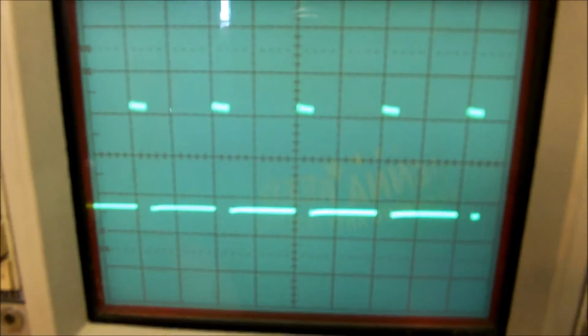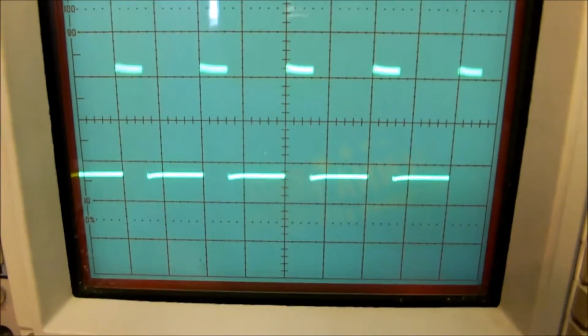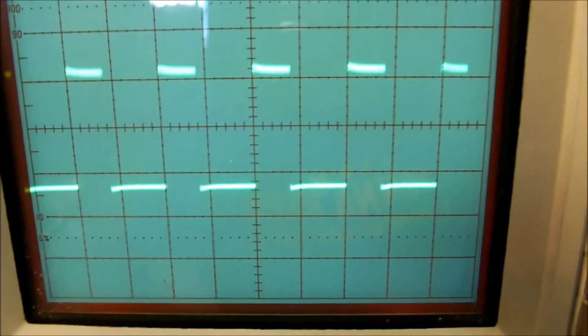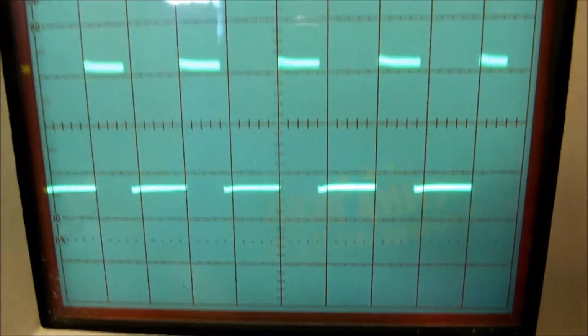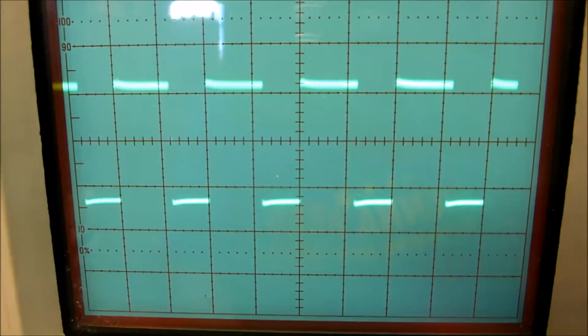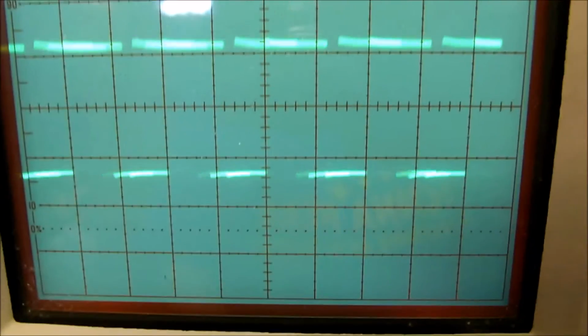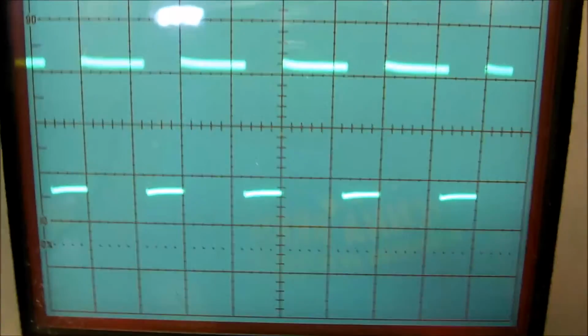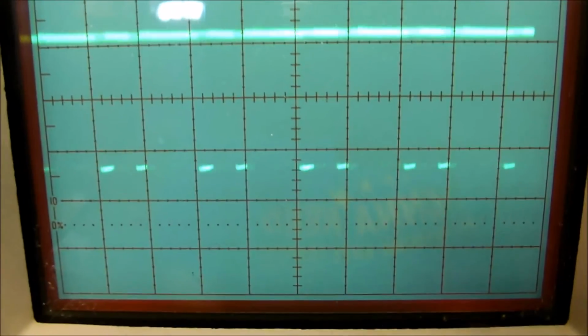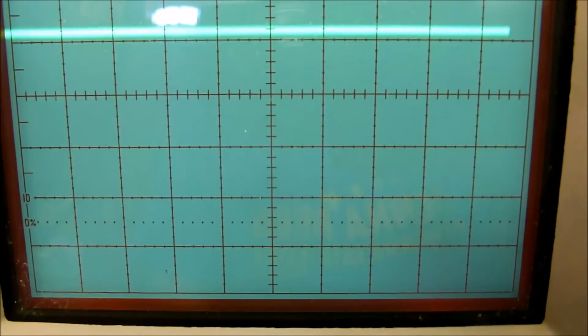Notice as I try to hold this up to get rid of that reflection. Notice as the pulse width increases, the motor will slowly start. I get to the start threshold, and it will continue to gain speed and torque. Actually, low speed will, but you always have a lot of torque, a lot more torque at the lower speed than a gasoline engine does. There we are, 100%.